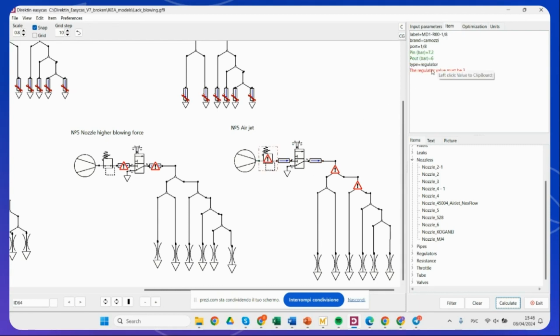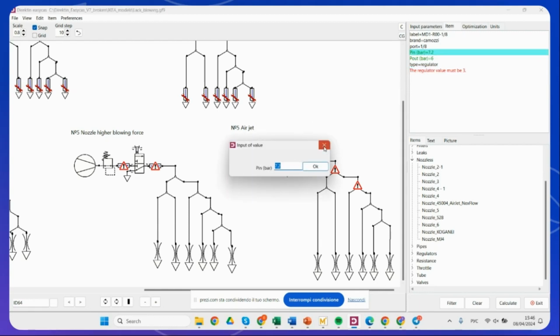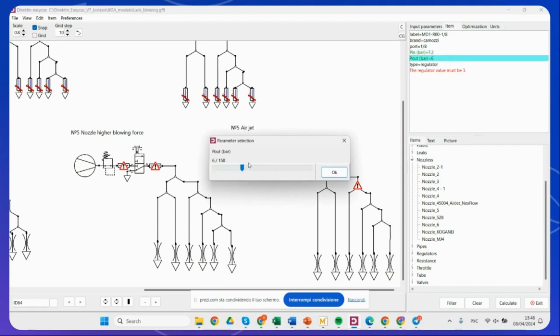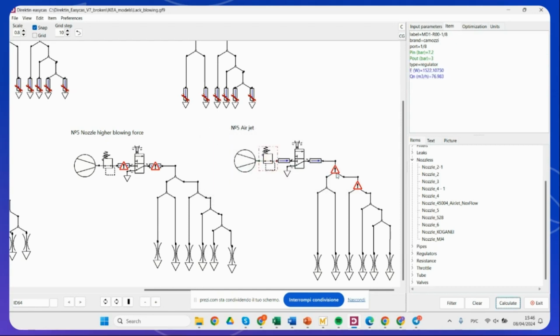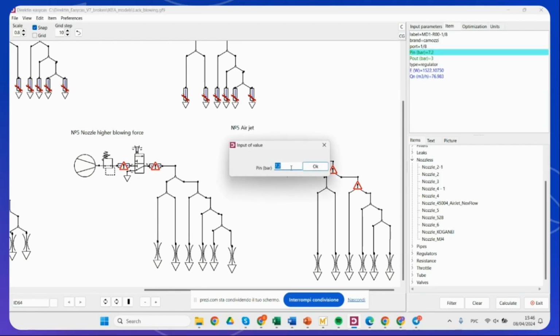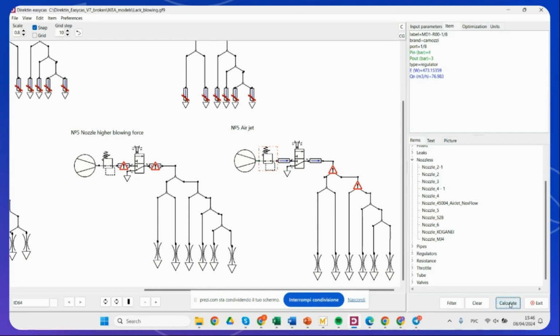And here it suggests that we reduce the pressure level. So we reduce the pressure level at the application. This is also one of the good ideas, to have the lower pressure there. Here you also should check the connectors. I don't want to go into details on the connectors. And let's see if we can have, for example, 4 bar for blowing as the compressor level.